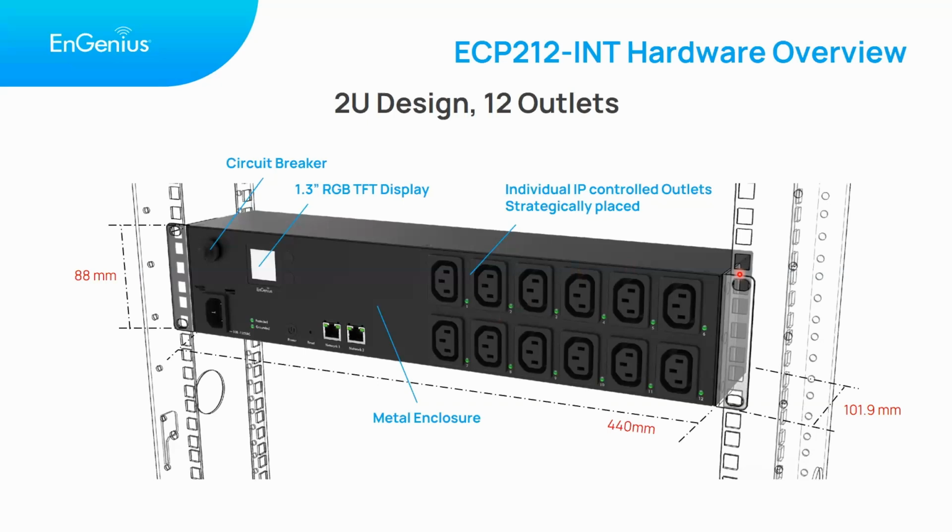Can the PDU be managed as a standalone device? So right now the PDU is available for managing over the cloud. I'm not sure if we will have an option for local management, but right now from the local UI you can only configure your network information, for example, IP address, management VLAN, and any specific gateway or DNS that you need to configure. That's what you can configure on the local UI. But in terms of the monitoring information, you can monitor your PDU information through the RFD or through the RGB display.